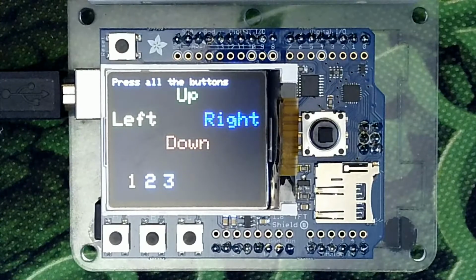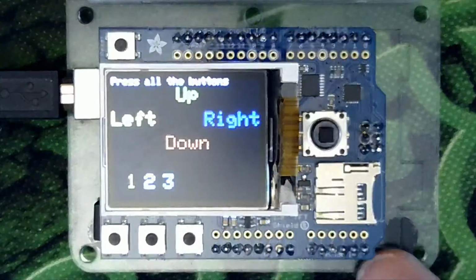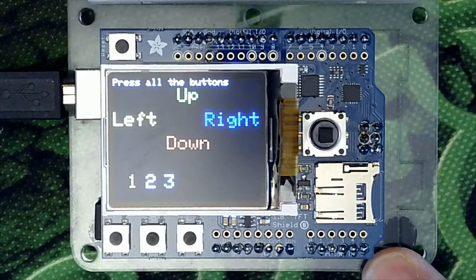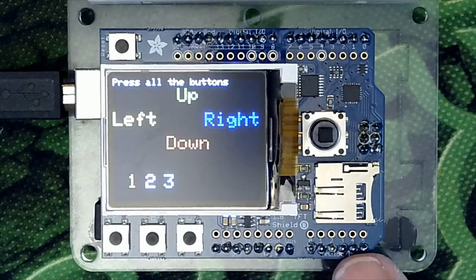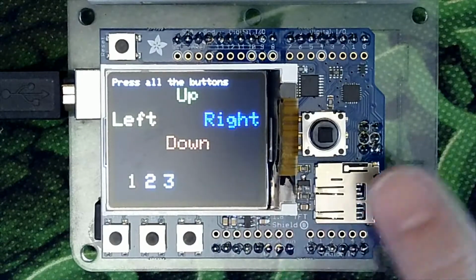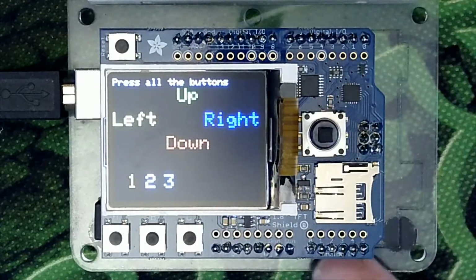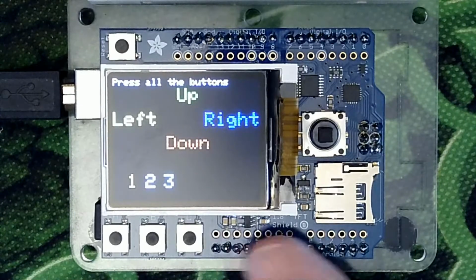So this particular display, let me point out some of the features on here. This is a very nice one. This one actually sits on top of an Arduino Uno. If you notice, it's the same shape as what our Uno normally is. So this one actually mimics that, and it's a direct plug-in. In fact, all these solder joints here and on this side line up with the existing pin boards that are standoffs that are underneath. We have a bunch of extended sockets on the Uno, usually by default. And these just plug directly into those. So I had to solder these headers on.